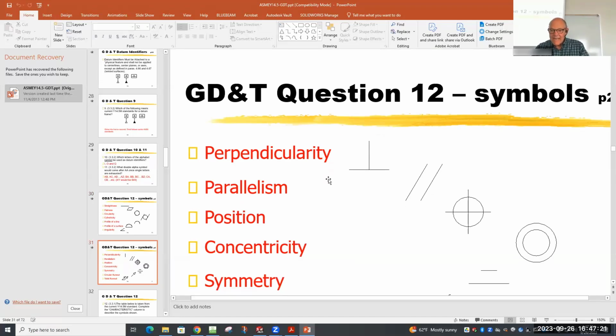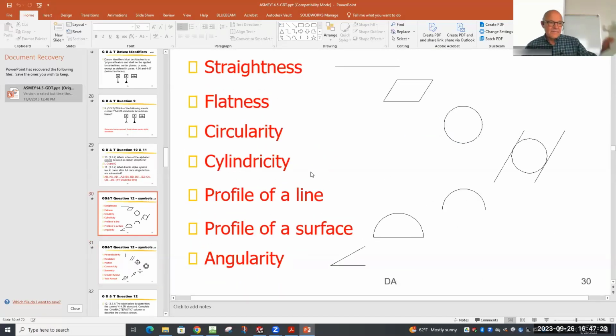So an angularity is something like this. If you got a part that looks like that, and I tell you that part's 30 degrees, okay, 30 degrees is fine, but the angularity controls the extent to which it falls inside a sandwich where the two slices of bread are exactly 30 degrees. So the measurement of this is you take a plane and another plane, and every part of that surface has to fall inside that sandwich. The sandwich is 30 degrees.